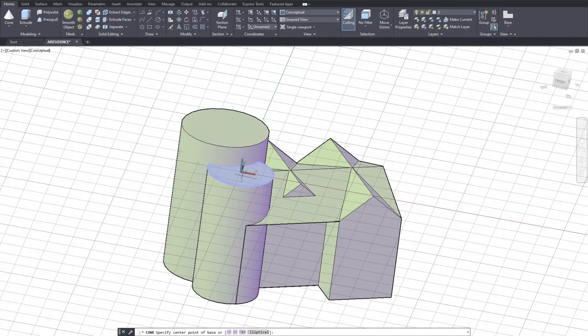And the first question AutoCAD will ask you is the center of the cone. Already knowing this ahead of time, I noticed that you have to be proactive. You have to make a plan ahead of time. So I knew it's going to ask me the start point of the cone. So that's why I put my UCS, I carried the UCS to the roof at the center of the roof. So I know already the center is 0, 0 now. 0, 0, enter.